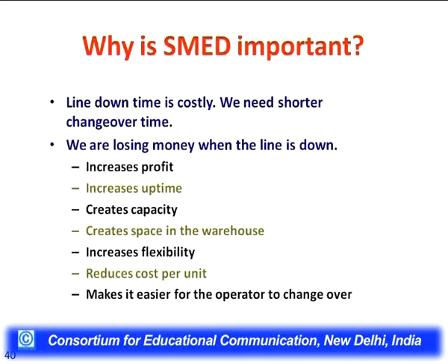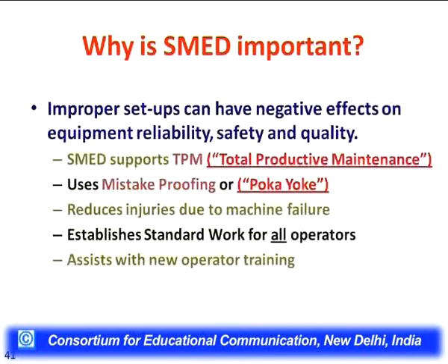Makes it easier for the operator to change over, because less time is required, everything is available close to his area of operation, and he will be happy to use it. It becomes easier for him to operate the machine. Easier to train new operators. As the changeover time and setup time is reduced, it becomes easier to train the operators also. Keeps all customers happy. The idea behind doing all this is to keep all customers happy. Why is SMED important? Improper setups can have negative effects on equipment reliability, safety and quality.